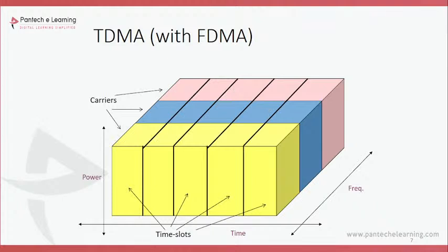Thus, the sequence of time slots and frequencies assigned to the mobile station is the physical channel of the TDMA system. In each time slot, the mobile station transmits a particular data packet. The period of time assigned to the time slot for a mobile station also determines the number of TDMA channels on the carrier frequency. In this period, the time slots are combined in a TDMA frame.